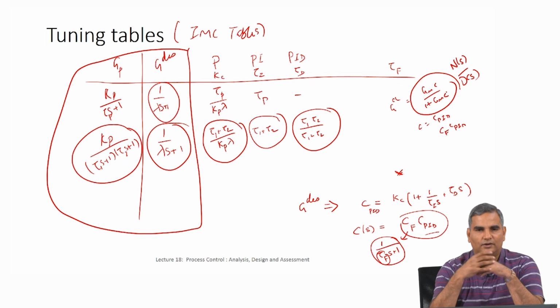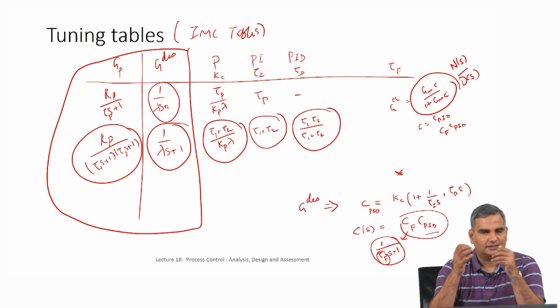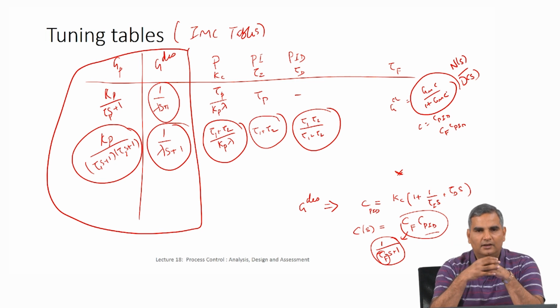Okay. So that is the beauty of this Routh table, and this table is needed because now I have coefficients which are functions of the controller parameters. So I showed you that if you have a polynomial, if all the coefficients are positive, then you go to the next step. If you have even a single coefficient which is negative, then we know there is at least one root in the RHP. So there itself we can stop and say there is a problem. But if all the coefficients are positive, then there is hope that there is no root in the RHP.